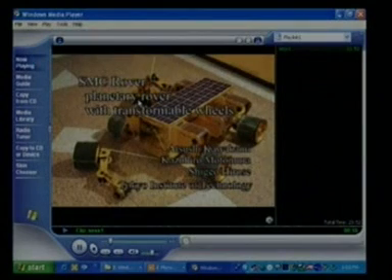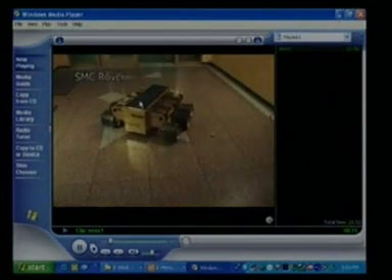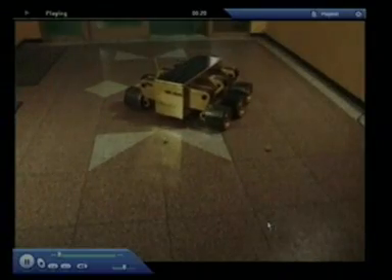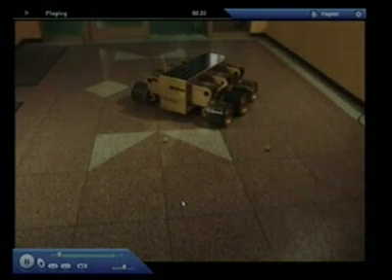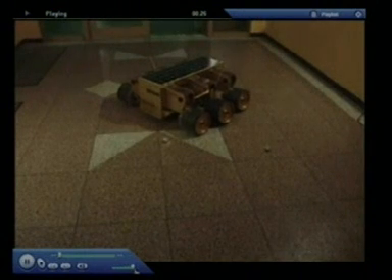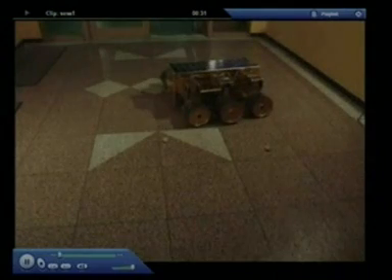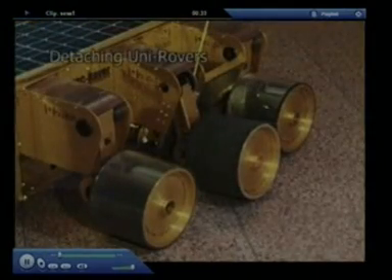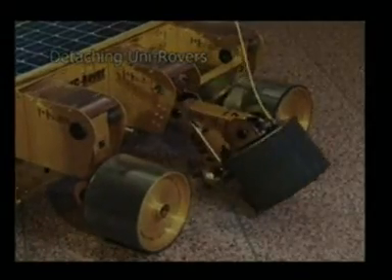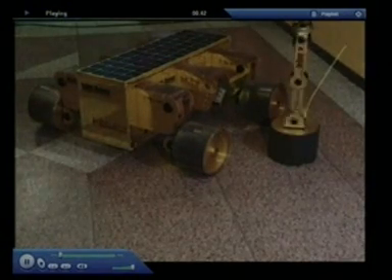Here you see how a baby robot comes out from the mother robot and does some task. It consists of a main body and unirovers, which are detachable wheel units. Unirovers are grasping the connectors on the main body. Since the main body of the SMC rover cannot move by itself, you see how it is doing the task. When the rover reaches the destination, unirovers are detached from the main body to do some other task. They release the connectors and stand up by themselves.